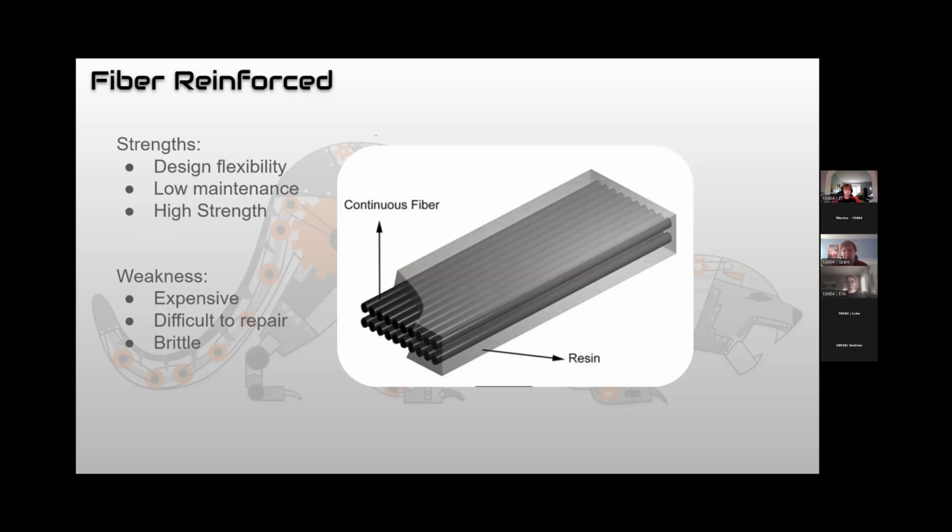And obviously, it will result in a higher strength as long as you do it with the right materials because it'll combine the strengths together and it should give you a high impact resistance against many different forces. Whether it be compression or torsion, it should help protect against those forces. But obviously, composites are more expensive than normal ones because you have to combine the cost of both of them, and then you have to worry about manufacturing them, and repairing them is a lot more difficult than a metal piece because it's a composite. It's made up of different materials, and you can't just slap on one material. You have to try to work your way around it, and often it's better to replace that part instead of trying to fix it. And they're also brittle, so they like to snap instead of bending.